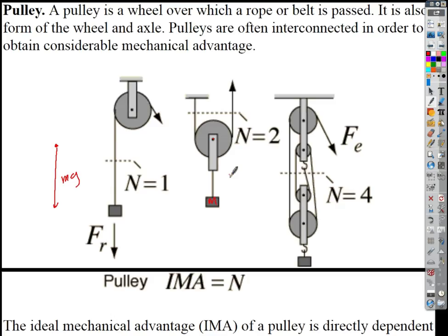Wouldn't it be impossible, if this is a fairly good pulley that has low friction, just for the sake of argument, let's say it has frictionless bearings, okay, for the tension to be bigger in one of these lines than the other line? What would happen if this tension were bigger than that tension? It would adjust itself to equal out, wouldn't it? Because it can turn freely, so it's always going to twist to equalize the tension. Does that make sense?